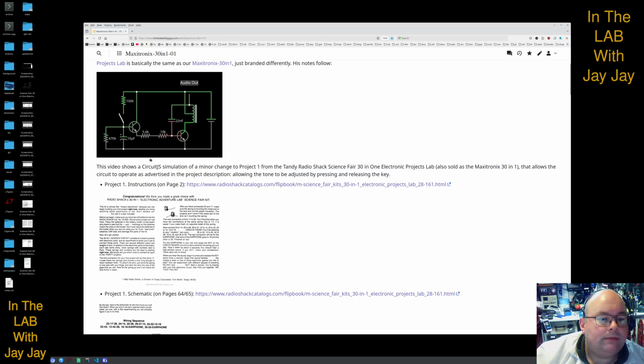So we're going to make this circuit together on the board in the booth, and we'll see if we can get that tone oscillating correctly. So this capacitor should be discharged through this resistor, so the key should actually cause an oscillation, which it's not at the moment.